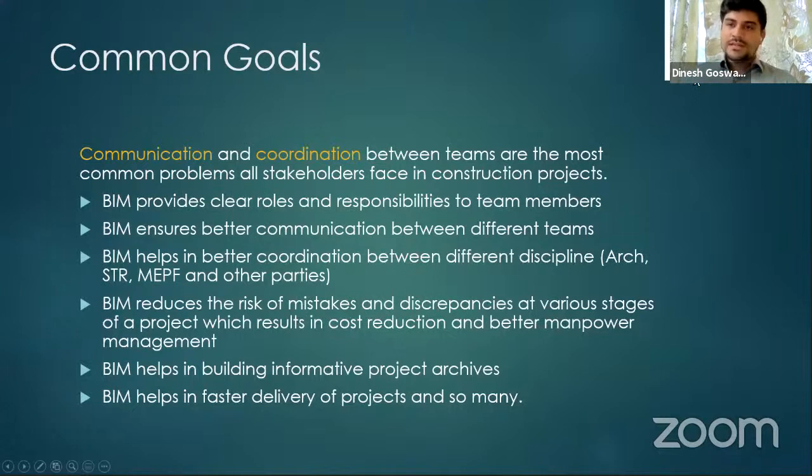So what happens next? Once we have the clash-free model, we'll generate the GFCs. GFCs are nothing but good for construction drawings. We can also create the fabrication drawings and the sub drawings, which can be executed on site. So after the model is clash free, we create these drawings. So this is the process.